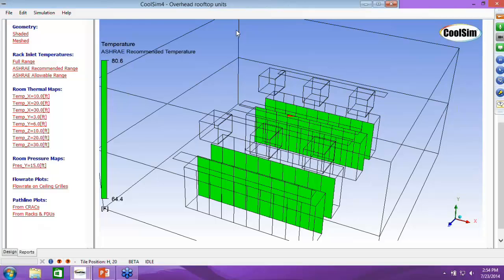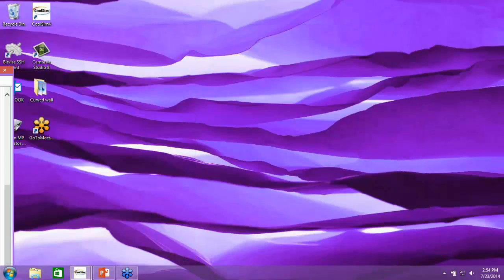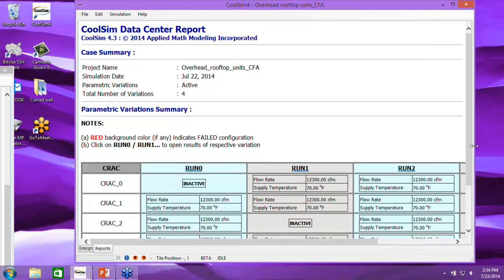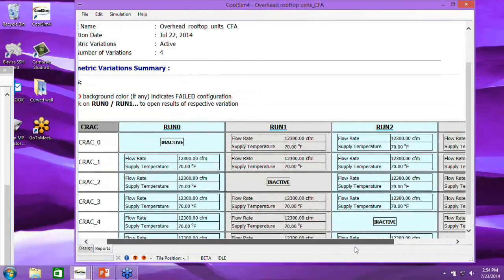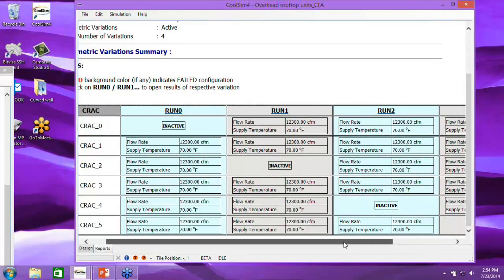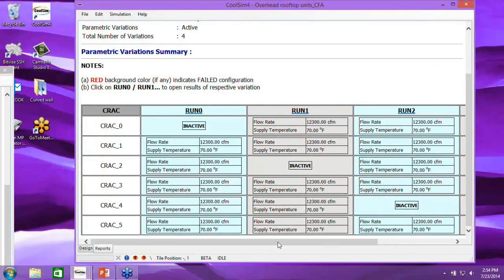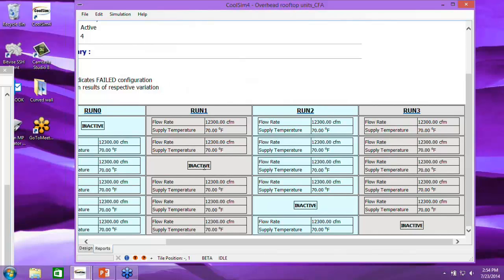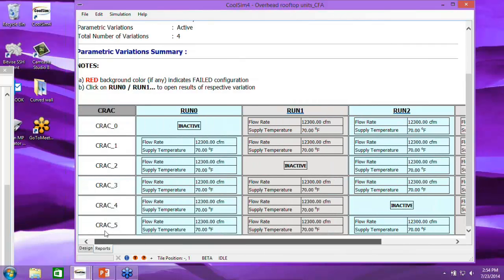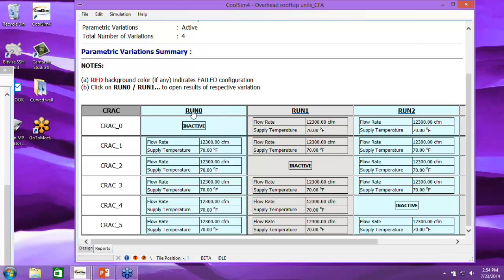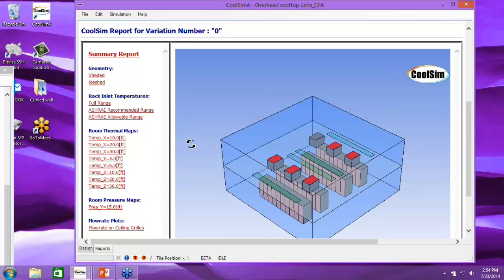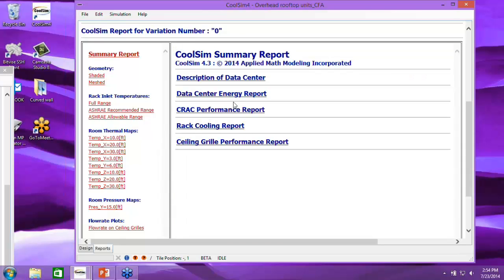Now the other thing I did here, Magnus, on one other run is I did a full failure analysis here. This is another one I ran since I spoke to you last, and we ran 4, and I round-robined the cracks. I turned them off. But I didn't do them all. I did the ones I was most worried about. I did the ones on the ends, right? Because the middle one seemed fine, but as I go to the end here and turn this guy off, I run into a little bit of trouble.